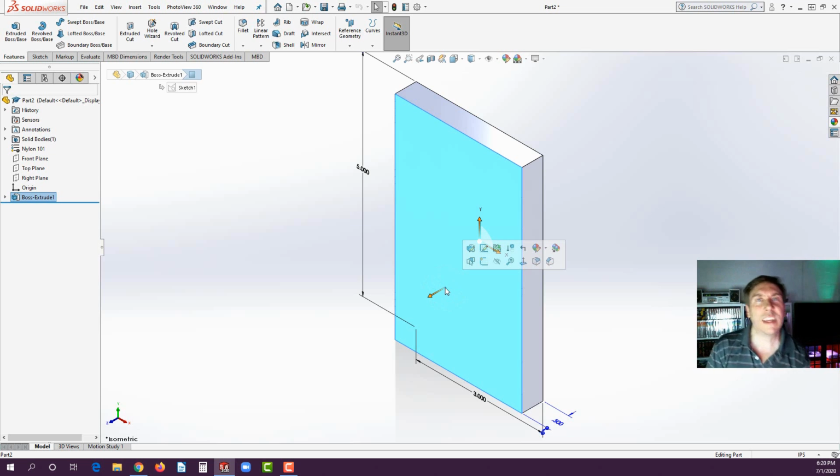Now, the last time we selected a plane to sketch on, note that you could select on any flat surface of the model. Doesn't matter what angle it's at, you can sketch on it as long as it's flat. If it's curved, you have to use a 3D sketcher maybe for that, but let's go ahead and click on it. Now you'll see that there is this toolbar that appears, the quick launch. There's a lot of options on here. What we're looking for is this sketch one.